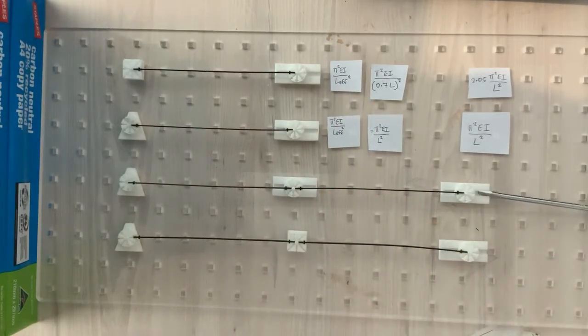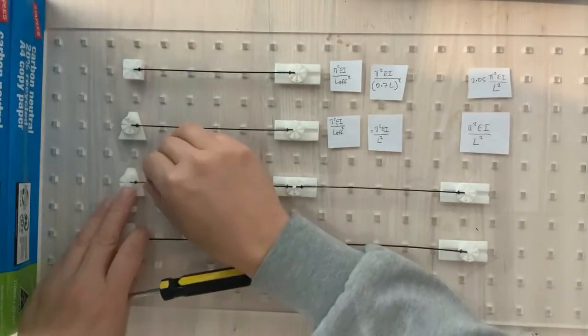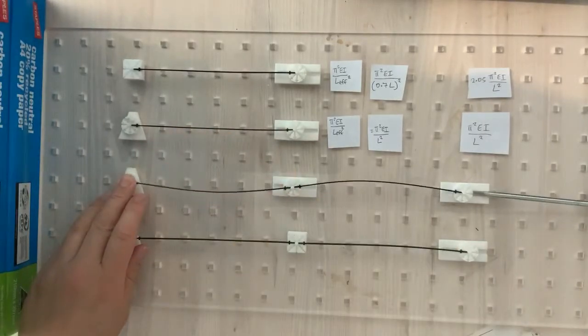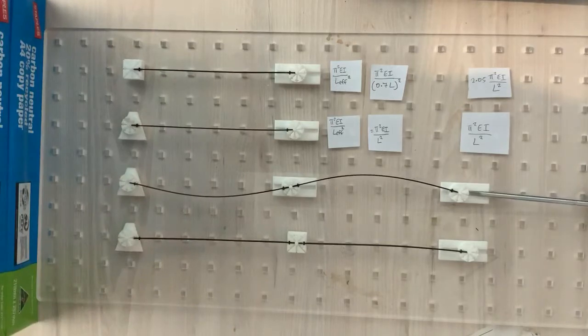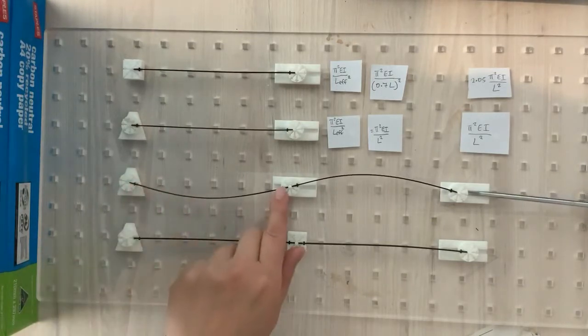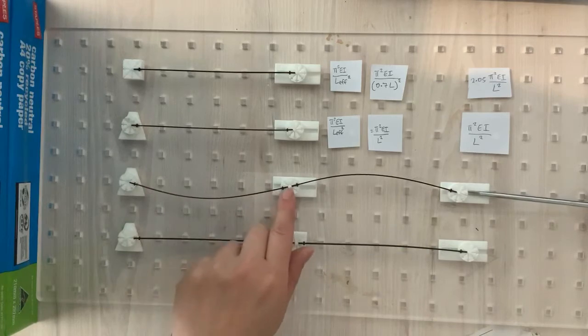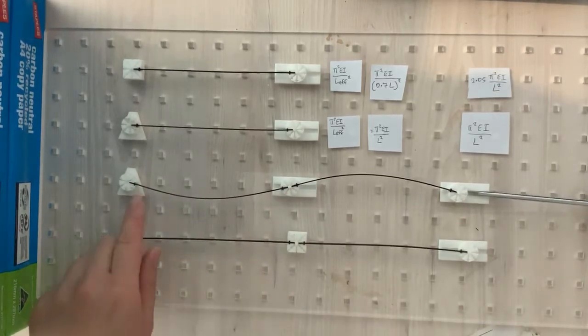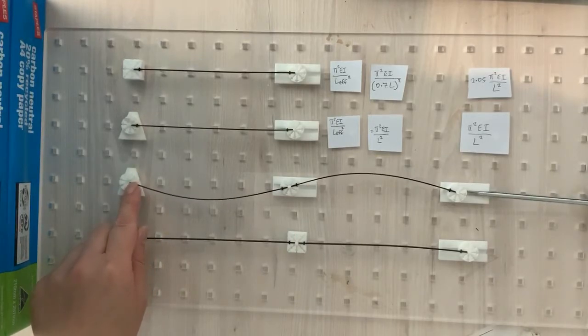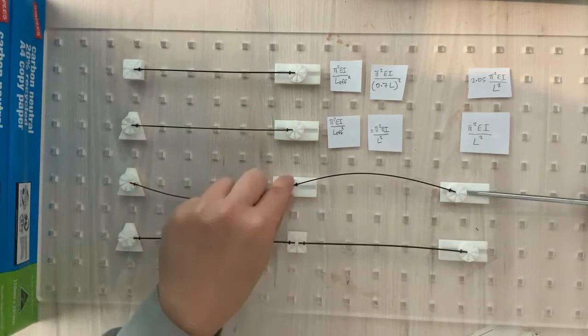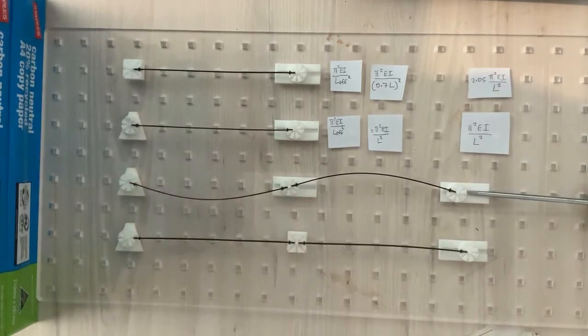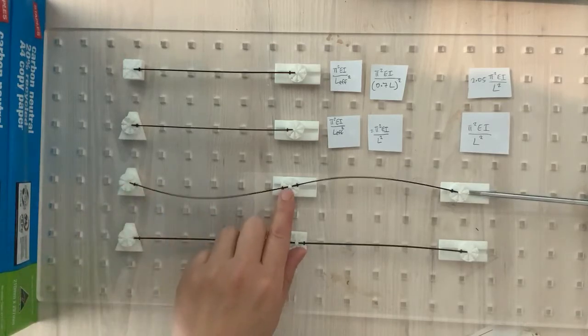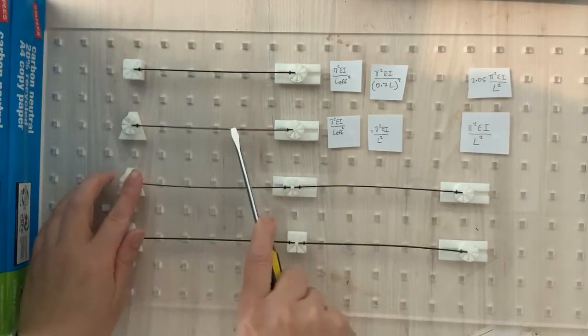When we apply that, we will see that this one buckles into 2 sine waves, and so the effective length is that distance there, or that distance there, which in this case turns out to be the same. So in this case here, when an engineer says what is the effective length of this beam column with a support that doesn't allow movement in that direction there, the effective length of this situation is that distance, or the same as that one there.